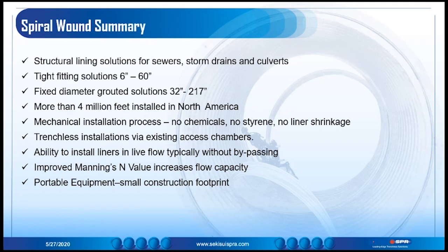When there's a defect in the pipe when using the static or the traverse winding method, how do you fix this? I can take that, Ryan. First of all, prior to installation, we're going to identify any defects that cannot be navigated by the equipment and the installation process. Those will be repaired prior to winding. If a defect appears during the installation, we will stop the winding, correct the problem, and then we'll continue to wind in the liner.